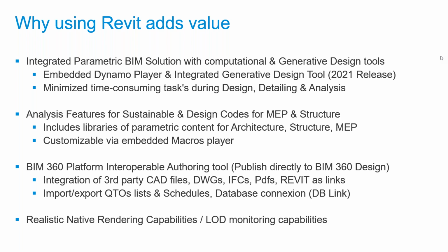Thanks, Nabil. And a question about some tools out there that people have been leveraging. For example, since 2016, we've had the NWD underlay that you can put in AutoCAD as well as inside of Revit. So you have the ability to bring in models that are in an NWD format, and Navisworks, of course, reads Revit and AutoCAD files. And with the right object enablers, you get all your properties in it. So you can bring NWDs into either. It doesn't clip properly for some views and such, but it does work for the design aspect of it.